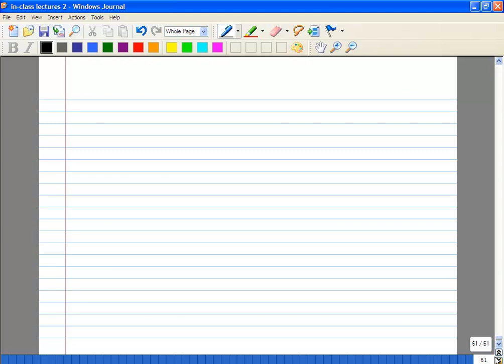So what we need is some way to do what is called power constrained noise optimization. That is, you have a certain upper limit on power you can consume in your LNA, and you need to calculate minimum noise figure based on that. It will definitely be larger than your Fmin, but you want to know by how much, right?